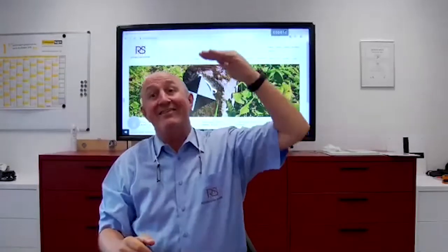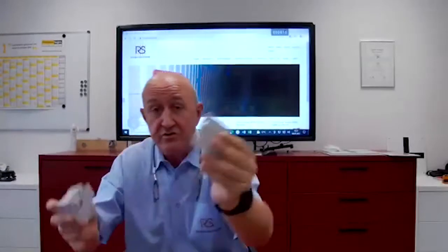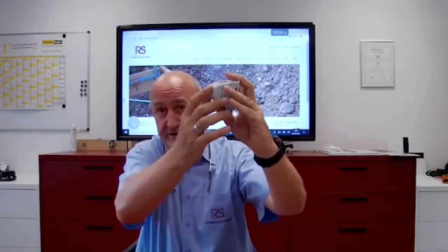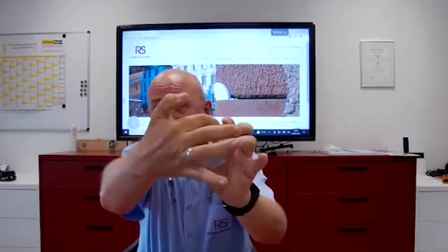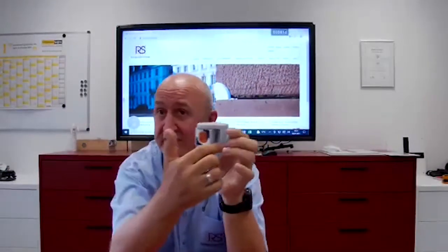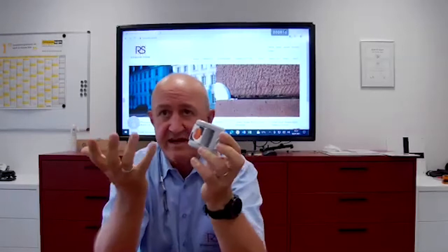That means first, maybe at a height a little bit higher than you can reach, so that no one grabs the prism, then in the middle of the building, and then, importantly, on the top of the building. The easiest way is just to glue one of these things, and then you use one of the prisms here. You can screw it in, so if it's stormy, it wouldn't fall out, or for any other reason. And as I told you, this is temperature and UV resistant.